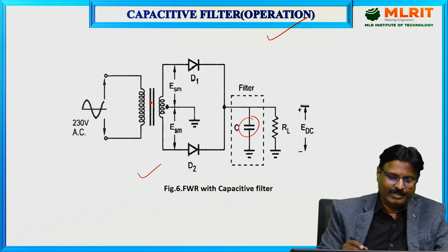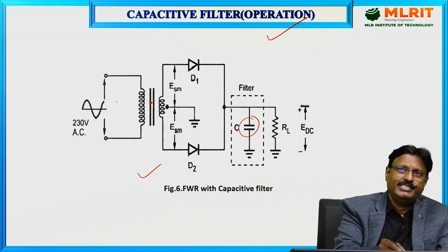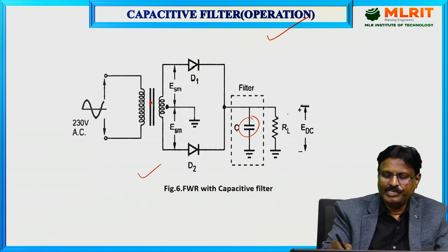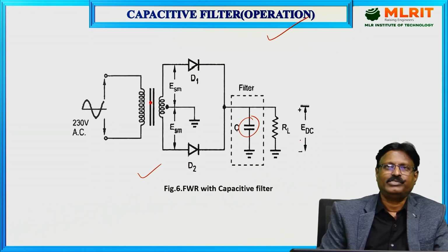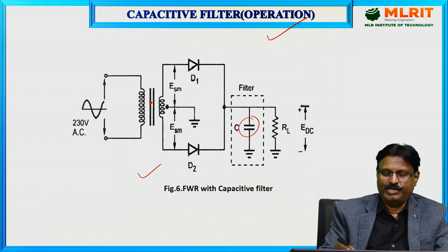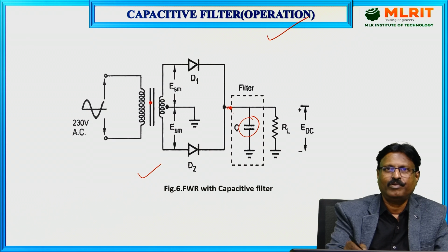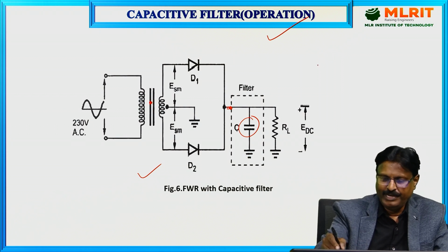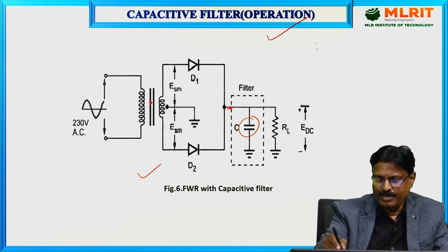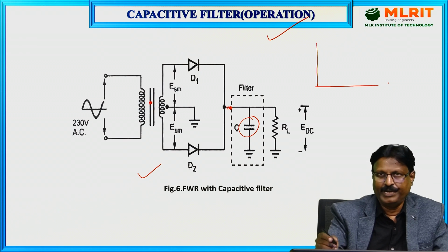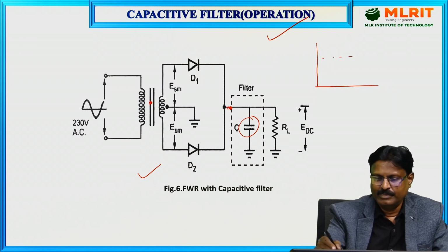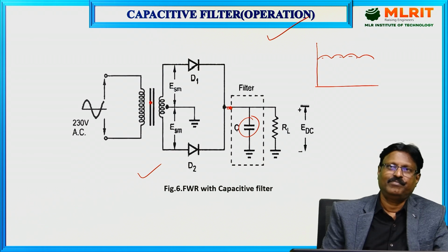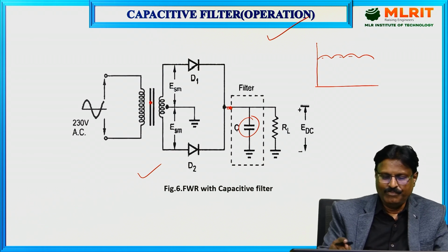Okay, so here the input signal is entered, which is an AC signal, and the output voltage across RL is a DC output voltage. Rectified output is given to the capacitive filter. If you observe the output here, this is a rectified output. Once again, that is provided to the capacitive filter. So from the rectified output, that is a pulsating DC, you will be getting a better version of the output voltage, which is closely approximating the DC signal like this. So somewhat like a ripple sitting over a DC shifted level. Okay. So if you observe the operation here,